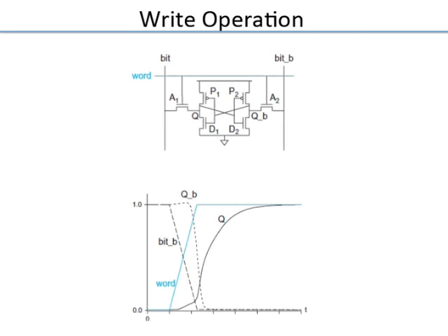In the case of the write, remember that the NMOS is very poor at conducting a 1. It is good at passing a 0. So let us say in this example Q bar is still 1 and Q is 0, and I want to write 1 to Q and 0 to Q bar. What you do is the bit line and bit bar are set up such that you have a 1 here and a 0 in the bit bar.